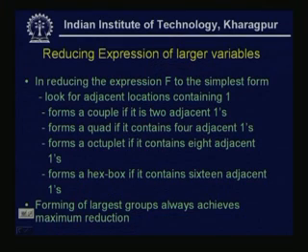Then we try to form the couple, meaning 2 adjacent ones, quad, 4 adjacent ones, octet, the 8 adjacent ones, or a hex, which contains 16 adjacent ones.